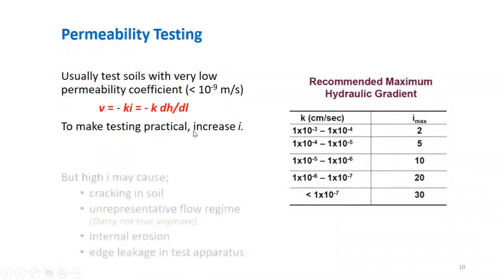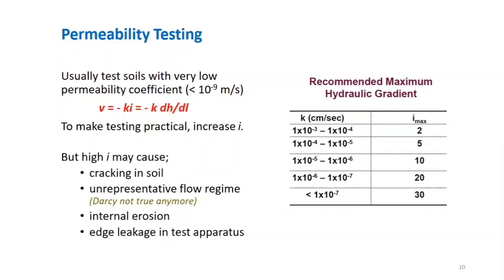But the problem is that once you increase i, this will cause an increase in flow, seepage velocity, and that will cause cracking in soils, and this will create an unrepresentative flow regime. That means you should not expect laminar or one-dimensional flow through the soils. So in that case, Darcy's law will no more be applicable.